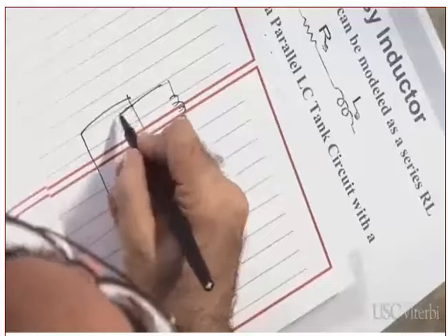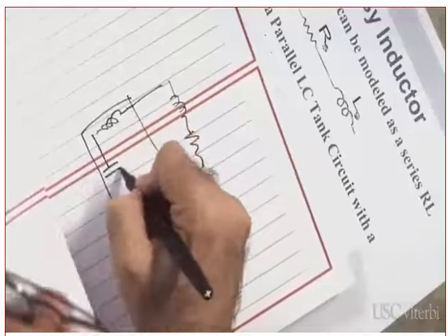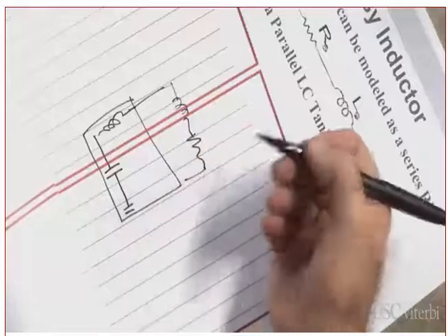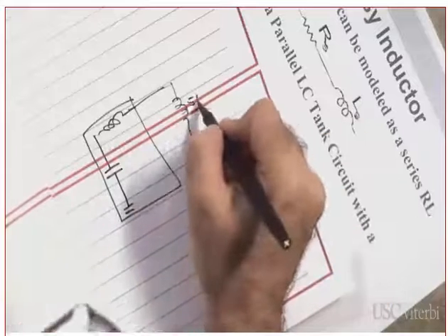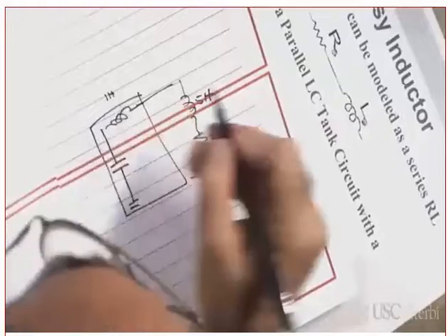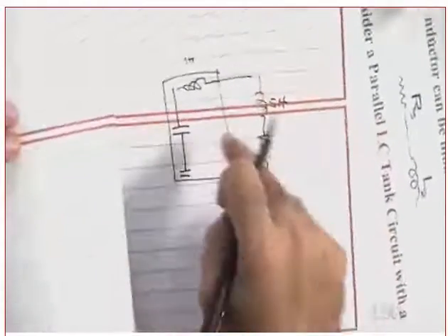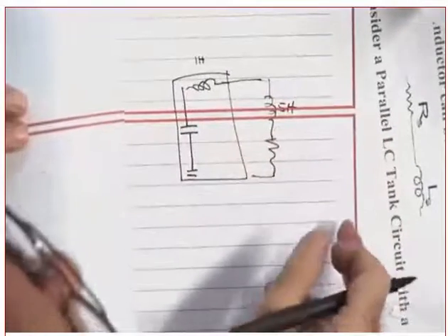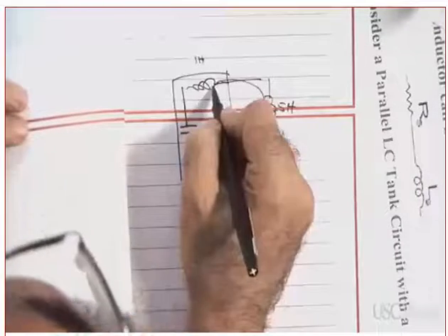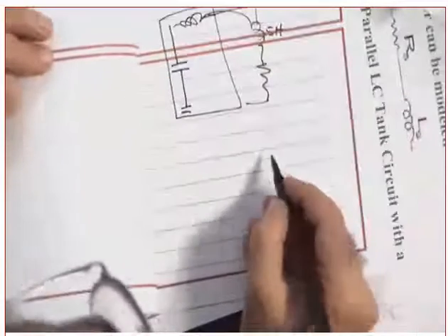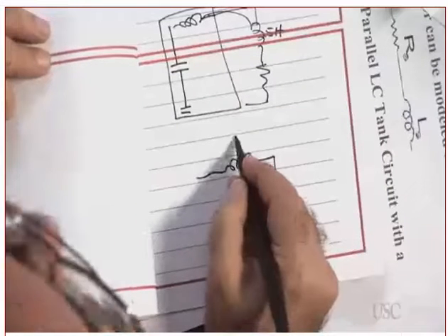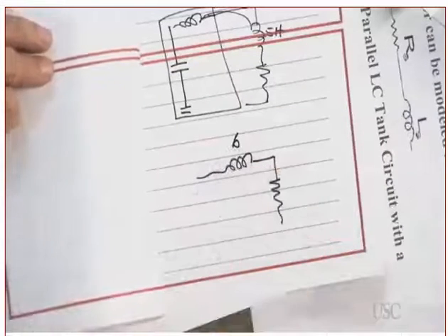Now let's assume the matching network is of the L type. I will show you what L type means. Is this an L type? This is called the L transformer. Let's assume this is 5 Henry, just an example. These are numbers. And let's assume this is 1 Henry. Omit this first. Do the matching of the resistive load, and then lump this with this guy. Which means it's as if now this is the matching circuit, which is 6. Did you get my point or not?